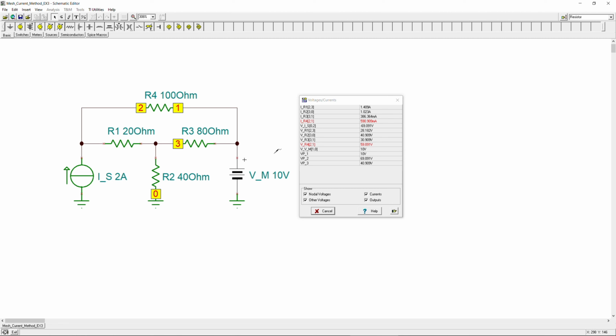What you also see is the following. This voltage here at this node is approximately 69.1 volts. Very close to what we have calculated in order to calculate the power delivered by this current source IS. So that is really nice to see also here. You can also, of course, check this node or that node. That is just 10 volts. You can also see the currents for the others. So that is really handy to see in the simulator.